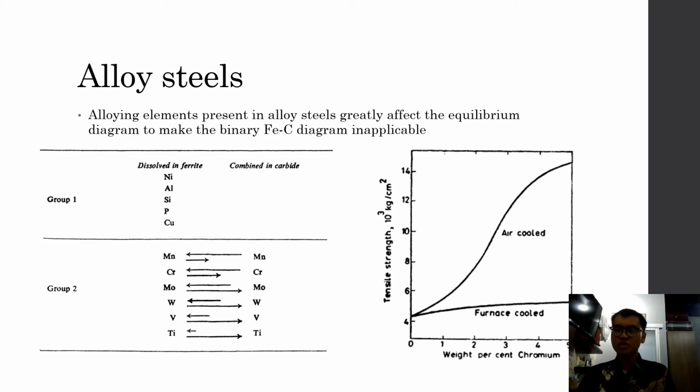Tungsten strongly increases hardenability. Silicon in larger amounts produces electric steels with higher electric resistance and better magnetic properties. When combined with manganese, silicon also increases strength, toughness, and ductility.